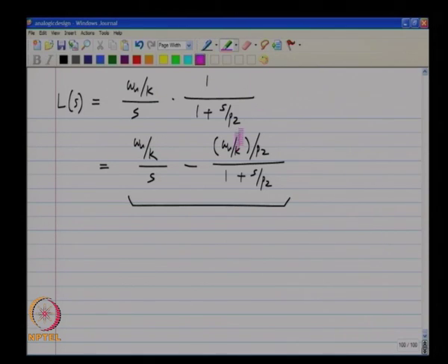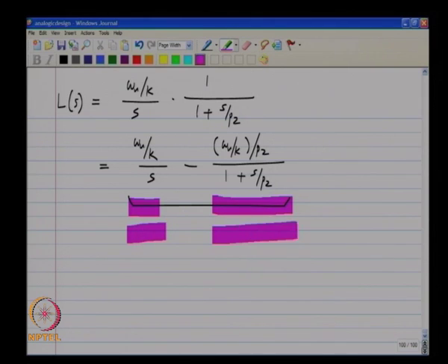So, you can verify for yourself that these coefficients satisfy the expression for loop gain. Now, the reason to write it down as in the partial fraction expansion is, now the step response of the loop gain is the step response of the first part of it minus the step response of the second part of it. Okay.